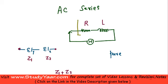The impedance of this one is R, the impedance of this one is j omega L. Therefore the net impedance of this circuit is simply Z equal to R plus j omega L. Let's mark my terminals: this is my point A and this is my point B. Then what I've found is my impedance across AB.